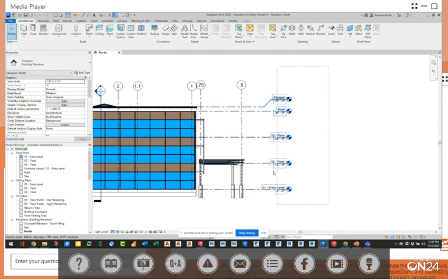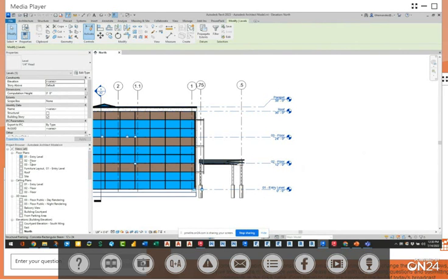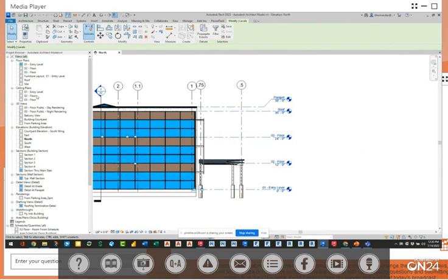You set these up, and then once you set these up, that's what it creates over here in the project browser. And again, I'm just going to turn off my properties temporarily here so you can see my browser. The project browser is what I tell everybody is what I call the table of contents. This is the file explorer that you would go and manage, 10 different DWGs or 50 to 100 drawings and cut sheets and all that to see what the actual project is, right? So everything in Revit in here kind of lives in this project browser or the table of contents.